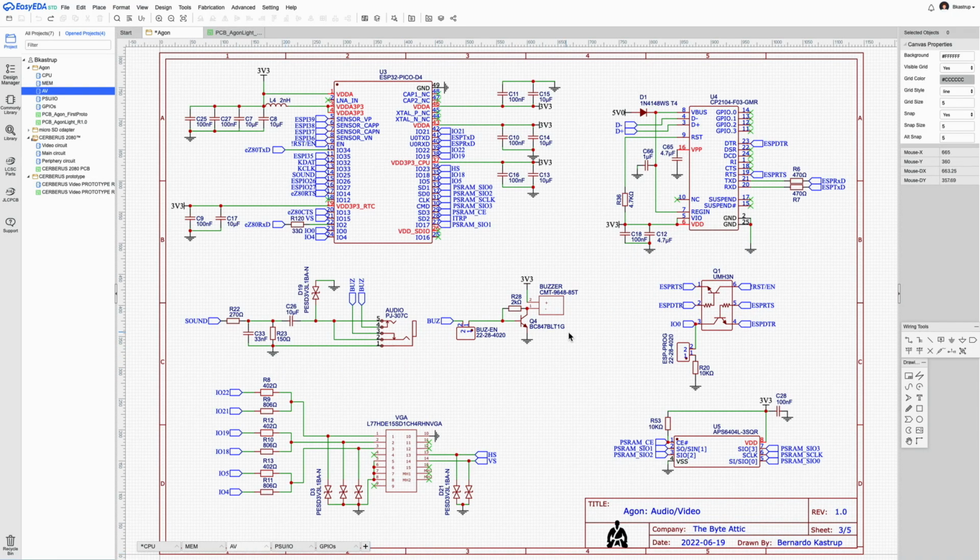Now let's go to the audio-video circuit. I will really not go into the details of this one, otherwise it will take forever. All these capacitors are bypass capacitors. Same reason you saw in the other slide. I am using now 2 values, not 3. There is a little inductor here, little bead, little coil, that has the same purpose. Capacitors resist changing voltage. They compensate for noise and variations in the voltage.